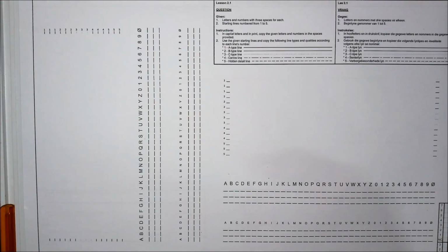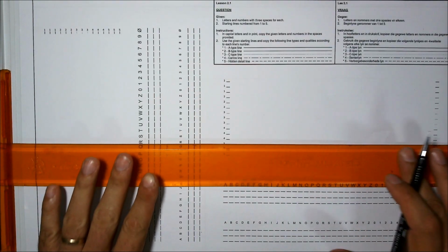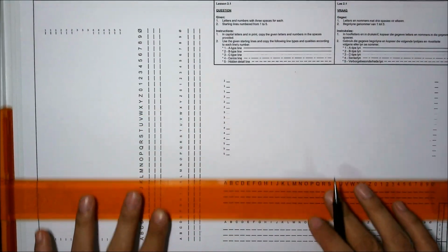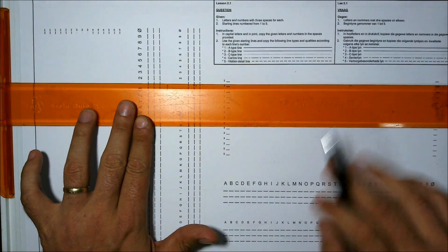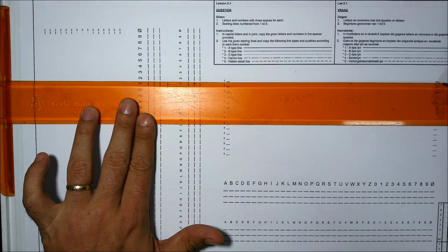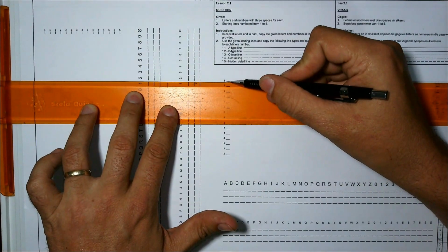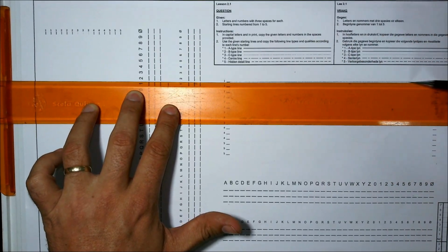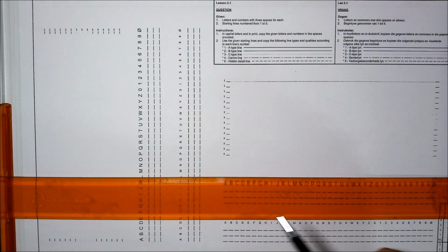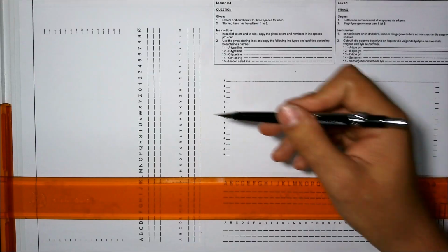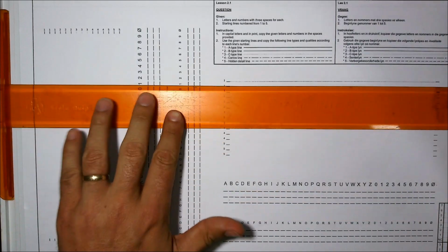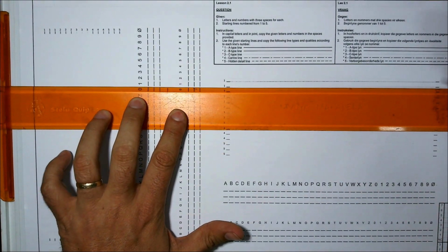Use the correct instruments. If this is fastened on your board properly and you are using your frame, then your T-square is moving up and down. You are going to line it up with point 1 with that given line, and you should see it lining up with a line on the right-hand side. This is considered an A quality line, which means you just draw a line straight through. I didn't try to push my pencil through the page. I just drew a standard line, with a bit of pressure, and that's what you should have. You are supposed to do this with all three of these.